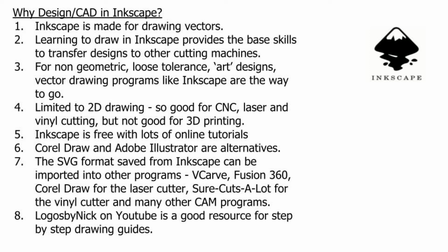Inkscape is free. There are lots of online tutorials out there to show you how to use it, but also some of the advanced functionality and the little special path tools and other things that are built into it. The scalable vector graphic format from Inkscape can be imported into other programs like VCarve, Fusion 360, Corel Draw, Sure Cuts a Lot for the vinyl cutter, and many other CAM programs. And if you're looking for a good resource, I highly recommend looking up Logos by Nick on YouTube for learning how to do various types of drawing in Inkscape.